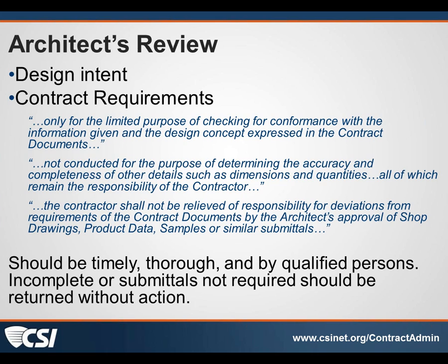If you get a submittal and it's not one of the approved products, return it quickly. Don't let it sit on your desk for 14 days if you've got 21 days, and then return it two weeks after you got it, saying you've got to revise and resubmit it because the manufacturer's not one that's in the specs. We should do these reviews quickly to help expedite the construction process.